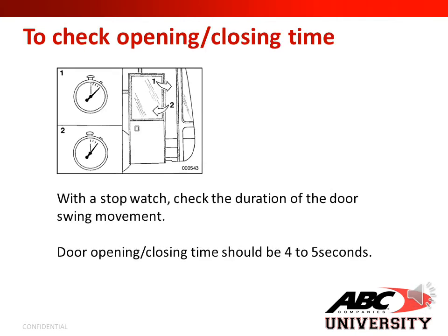To check opening and closing times, with a stopwatch, check the duration of the door swing movement. Door opening closing time should be 4 to 5 seconds.